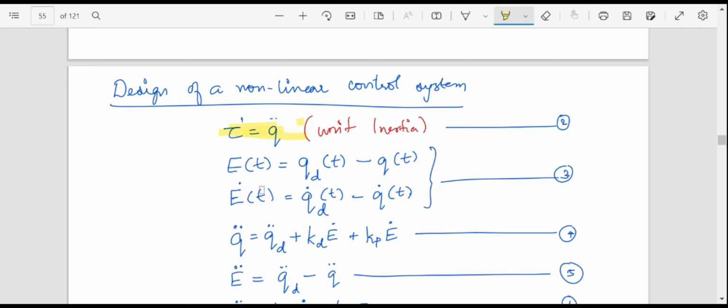When we calculate the error coefficient, the servo errors of position and velocity are given here. This is the servo error for position, and this is the servo error for velocity. This relation, which has been derived, shows us the output of the servo portion is the joint acceleration.